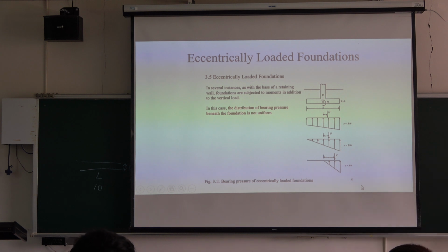But when we are dealing with the center like this, if the loading is at the center, we will assume that the distribution here is uniform, right? Like we will assume it's like this. The pressure is uniform because the loading is at the center of the foundation. But in most cases, when we deal with foundation problems, it's not the case. Q may move here, so the distribution will not be uniform. So it may be uneven in shape.